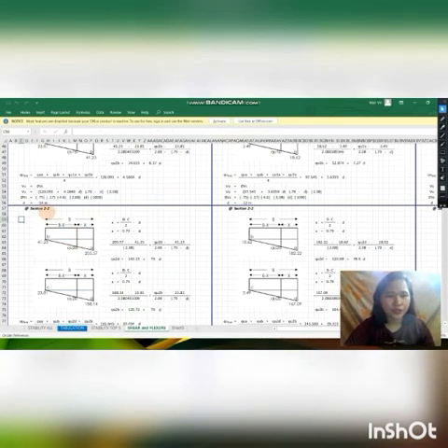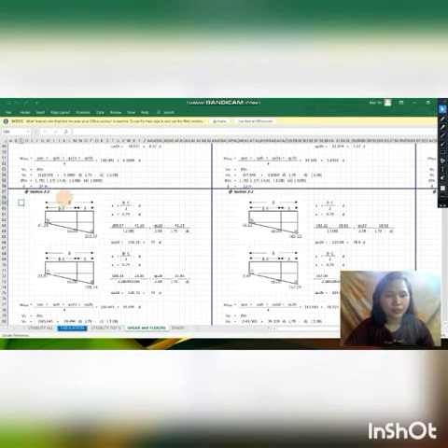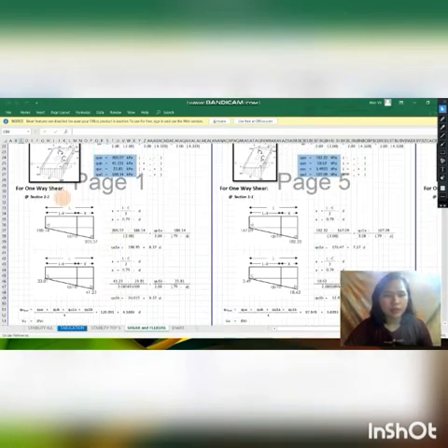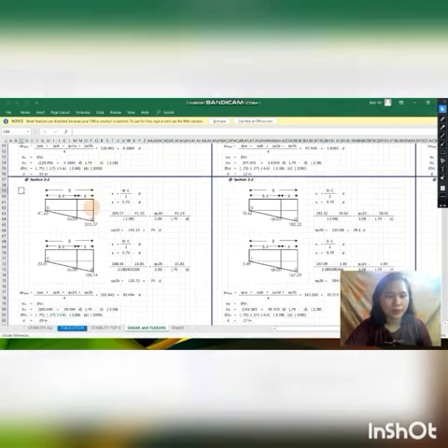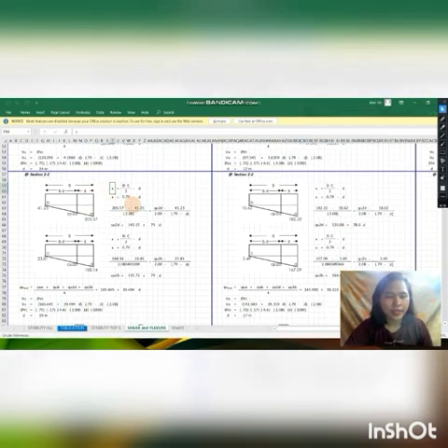So for our section 2-2, we take the side of BA because it has a larger soil pressure, the same as our one-way shear at section 1-1. So for our x, we have this equation, b minus c all over 2 minus d. We will arrive at the same answer, 0.79 minus d.